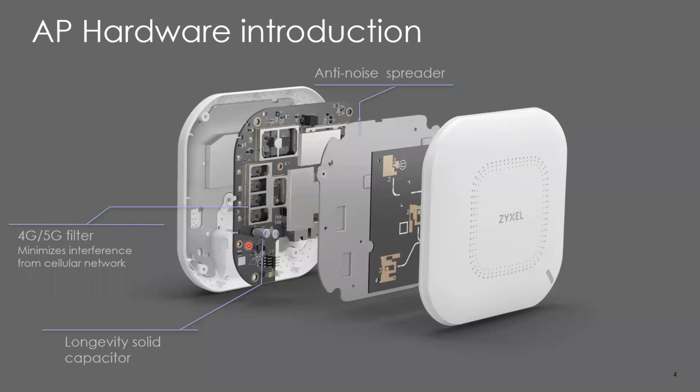And then lastly, on our products, we do not use any electrolytic capacitors. We only use solid state capacitors. Behind heat fatigue, failure of your capacitors is probably the next most common cause of failure on solid state components. The electrolytic capacitors are filled with sort of like a saltwater solution, and they can dry out, they can leak, they can expand due to steam being created inside them. So by eliminating electrolytic capacitors, it helps us increase the life of our products.